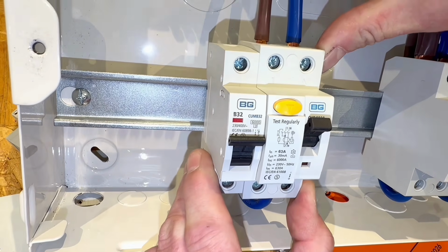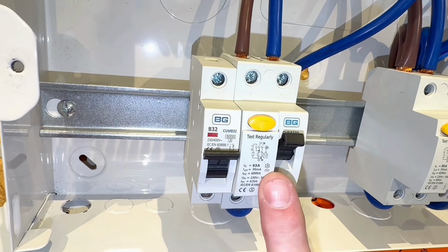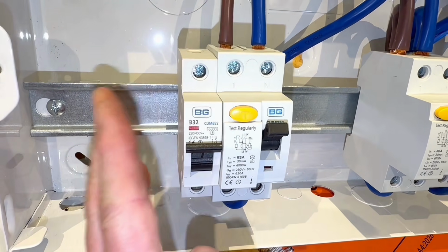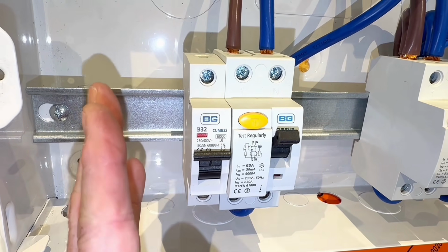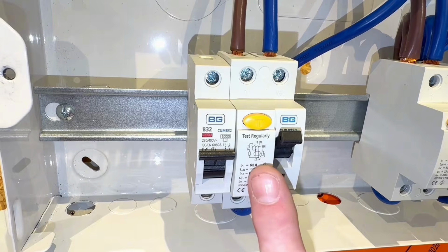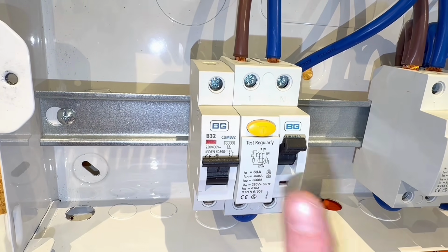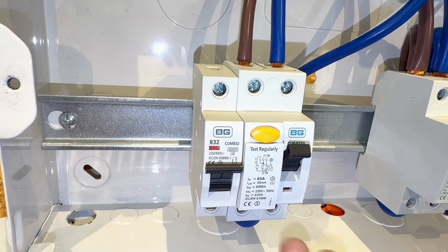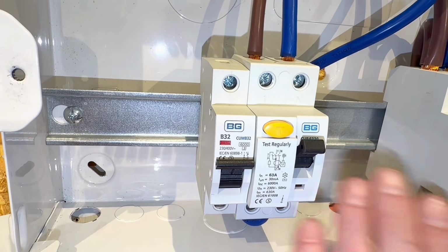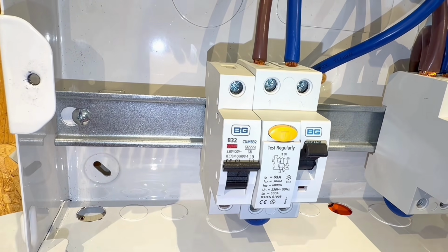So back in the day with these old split load boards, which we've said now need to be removed, there's only one RCD protecting many circuits. If that installation had, say, on the end here, an MCB going off to feed a solar inverter, the MCB and this RCCB are both bi-directional, and that installation obviously is correct. We haven't got to worry about those devices. So strictly speaking, it's only the next iteration after this, when we went to full RCBO boards, that we have the problem and we have to identify them.